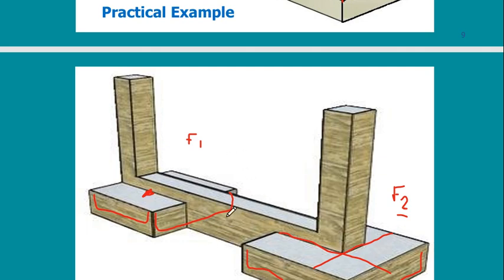But now I have also the strap beam. This is the additional point that I need to design here. F1 and F2 are normal isolated footings. The only difference is that I shifted this column to be an imaginary column with an eccentricity here. And I designed F1 based on this new load, and F2 based on the new load.